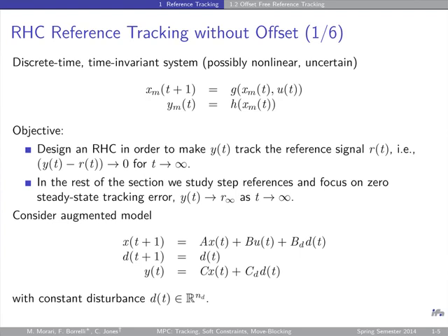Let's see that in the next slide. I have now here my X target and my U target, which are the X and U targets from the previous slide, the system of equations that I repeated down here. So how do I get no offset? What to do? First of all, I have to use this special observer that I showed you with the augmented state, where I estimate the disturbance of the state. That gives me an X head and a D head. That's my estimate. And then I can use this D head here.